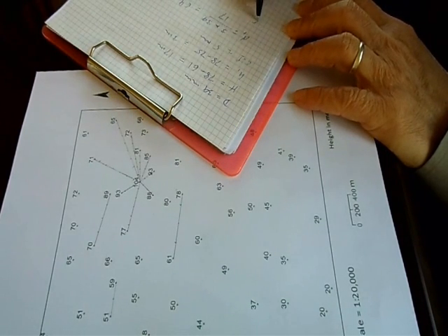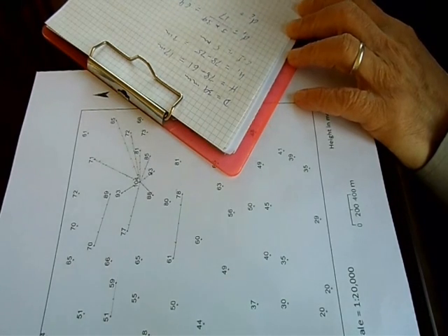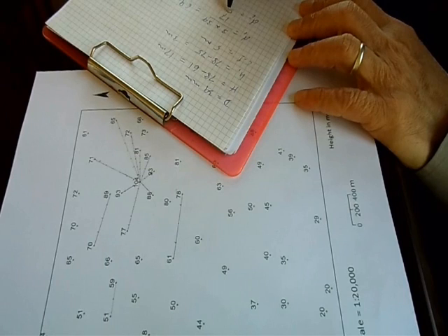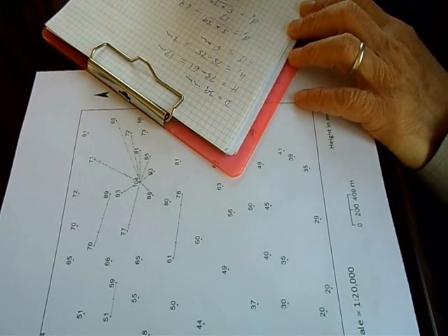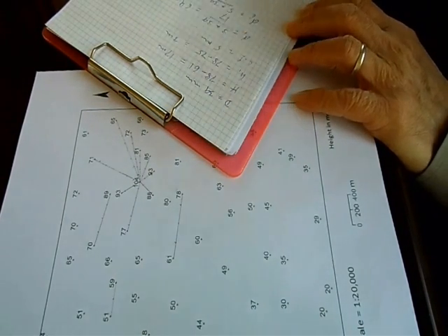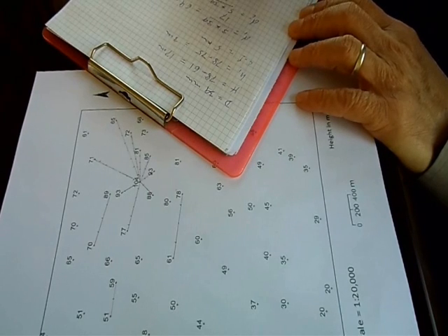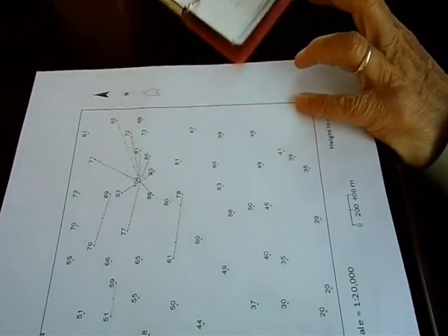Then Di, which equals D2 and D3 in this case, equals the contour interval 5 times 39 over 17, and this gives 11.5 millimeters. So D2 equals D3 equals 11.5 millimeters, and D1 equals 6.9.